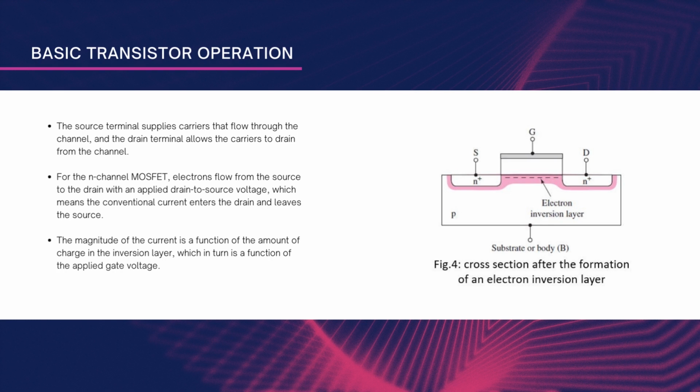So, as I have told you, the direction of the current is opposite to the electron flow. Here, the electrons are flowing from the source to the drain terminal via the channel. Therefore, the conventional current direction will be in the opposite way. So, you will generally find the conventional current in the downward direction in the case of an N channel MOSFET.